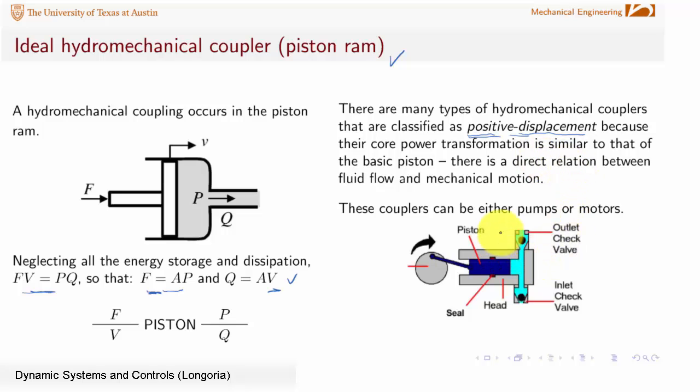Those form the working principle for a lot of machines. I'll show you a few here. Basic positive displacement piston machine, right? We're talking about just modeling, in this case, just the piston action. In order to make this machine work right, we'd have to drive the piston back and forth, and also we'd need to have, in this case, if we were pumping fluid up to a higher pressure, these little check valves that would allow, as you draw the piston back, flow to come in, and then when you put the piston back down, that closes this one and allows the flow to go out that way.